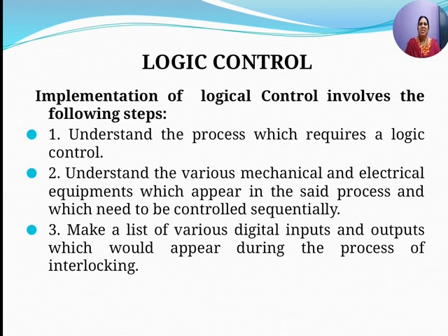There is a different set of interlocks we will be using in this process logic. When it's not true, the device needs to be stopped for the purpose of safety or preventing any damage to the device. This abrupt stopping of the device is called tripping.